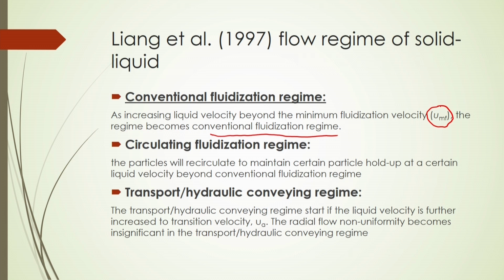That particle hold-up is the volumetric concentration of particles inside the bed, calculated as the volume of solid particles out of the total volume of solid and liquid inside the bed. You have to maintain this particle concentration constant at a certain liquid velocity,